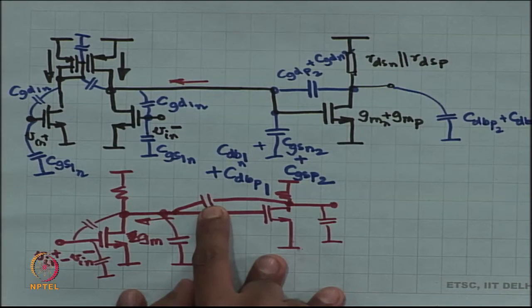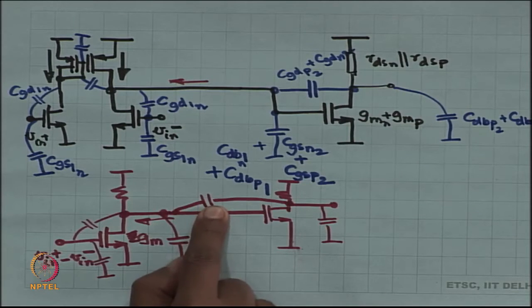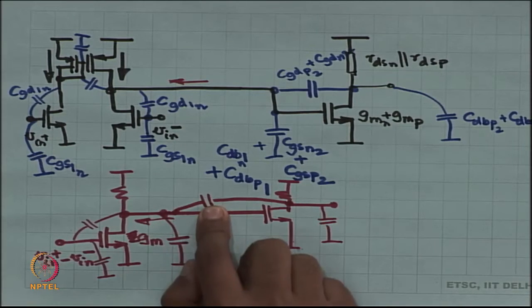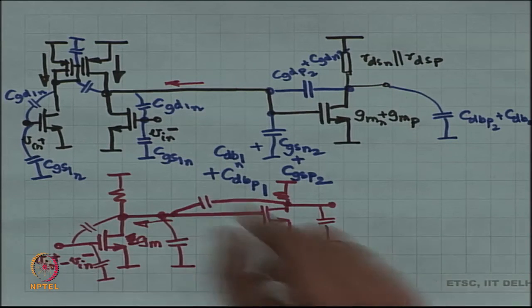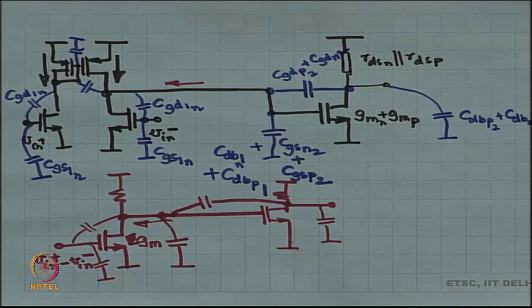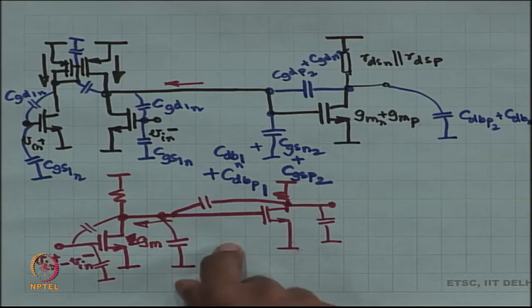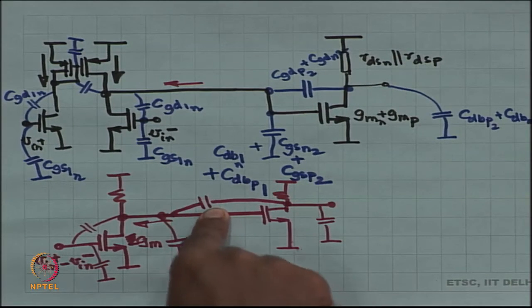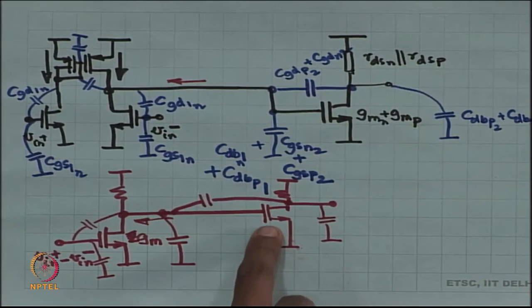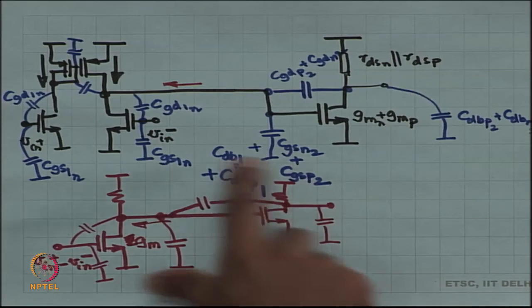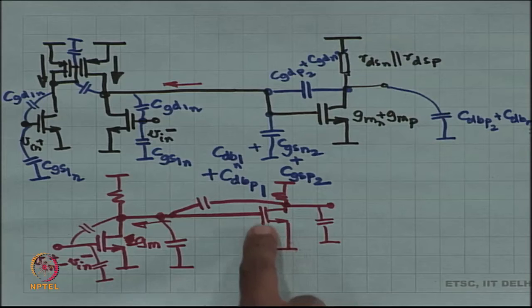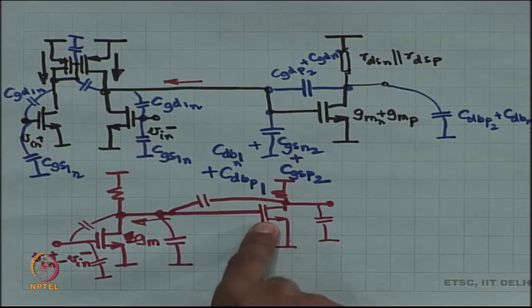However, we have added on to this capacitor value. We have increased this capacitor value. It is no longer just a parasitic overlap capacitance, it is no longer gate to drain capacitance. By doing the compensation exercise, we have added extra stuff over here, and that is going to make the second right half plane zero, the location of the second right half plane zero, if you remember.